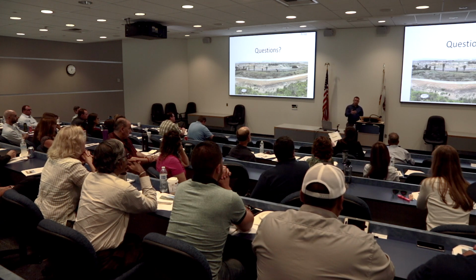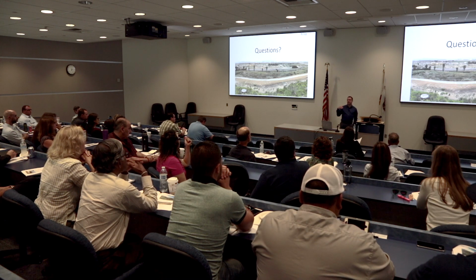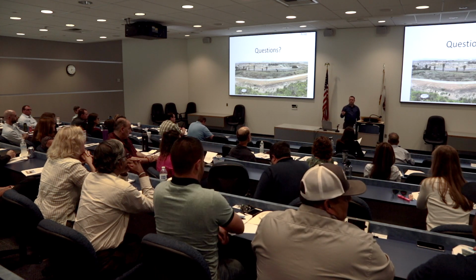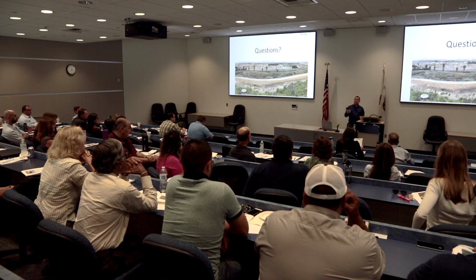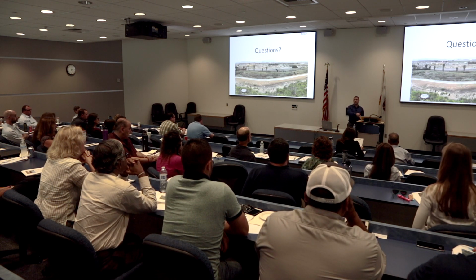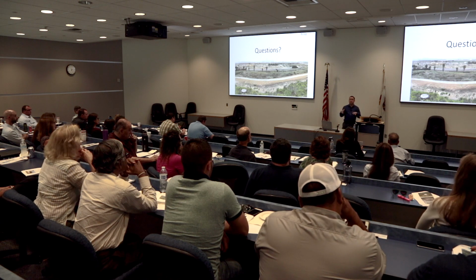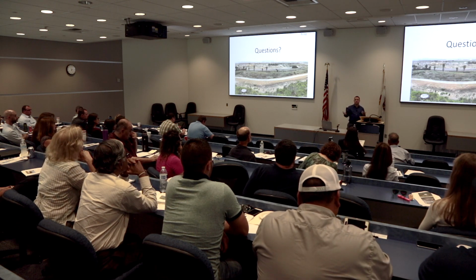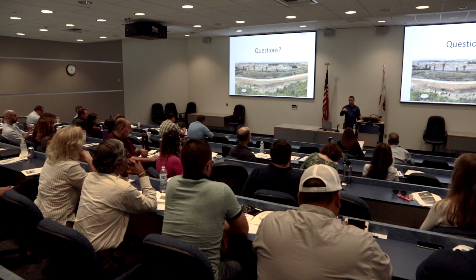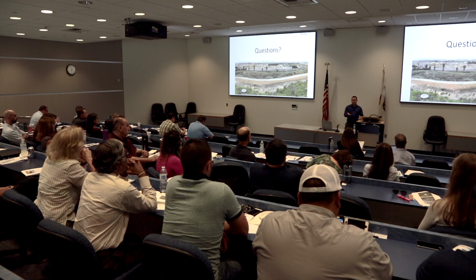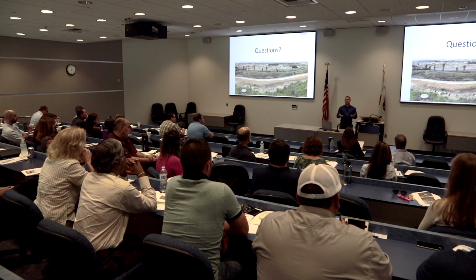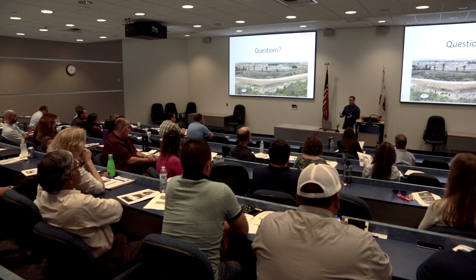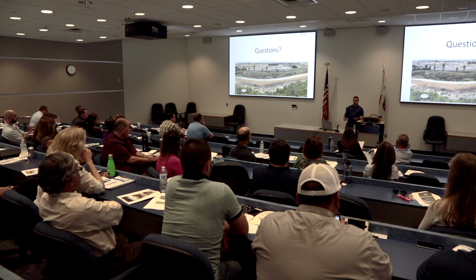And we had told them, it seemed kind of high for us, like that whole area just seemed kind of high. We told them, make sure that you test in a couple different areas and make sure that's the case. Mainly because we knew what was on that site before, and when they demoed a portion of that site, they didn't demo everything. What was on that site was underground tunnels. They knocked off the top parts of the walls, and then they filled everything in, right? So there were still basically concrete channels underneath there.